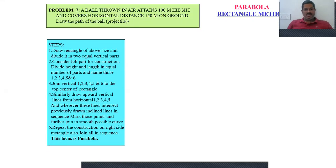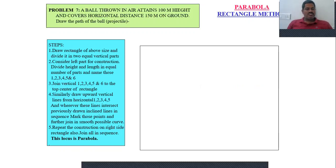Now draw a rectangle of height 100 meters and length 150 meters, with the given dimensions. Then divide the height into convenient equal divisions. Say in this case it is 6. Similarly, divide half of the length of this rectangle into the same number of divisions that we have done in the height, so a total of 6 equal divisions.